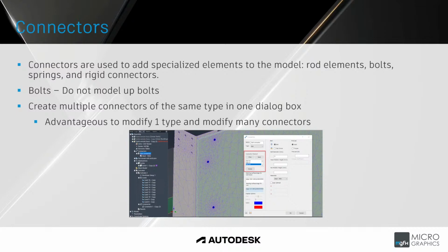For instance, if I've got bolts and nuts, and say you've got your assembly and you put 1,500 nuts and bolts in, that's 3,000 parts, which if you then have to do an idealization for that, it's going to have to idealize 3,000 parts, and when you run your analysis, it's going to have to do calculations on those little 3,000 parts that you've got over there.